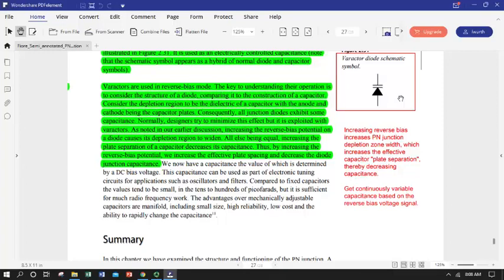There's a time constant associated with that, and so there's a rate limit to how fast it can change direction. So it's literally the capacitance of your PN junctions that gives rise to all of the performance specs associated with switching speed and time rate performance. So it's not a mystery, it's just the capacitance of the junction.